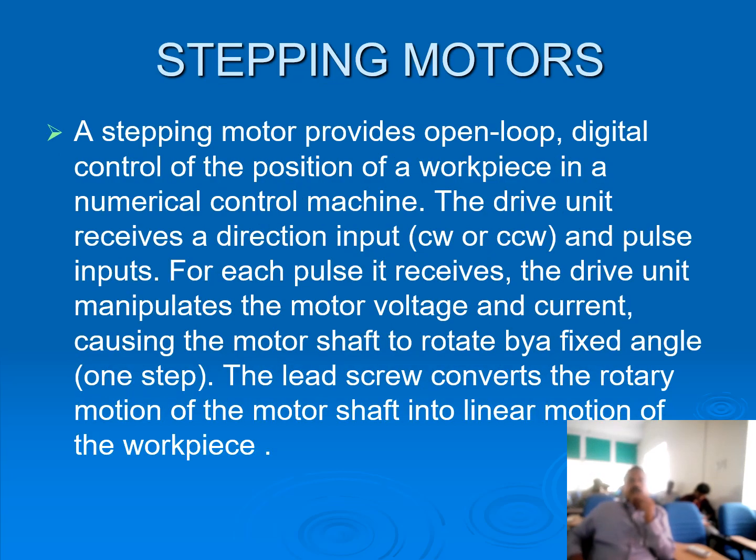The stepping motors, or stepper motor as they are also called. A stepping motor provides open loop digital control of the position of a workpiece in a numerical control machine. That is the purpose of having a stepper motor. The drive unit receives a direction input, clockwise or counterclockwise, and pulse inputs.